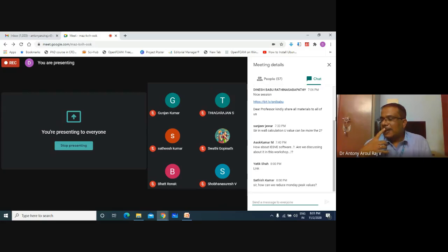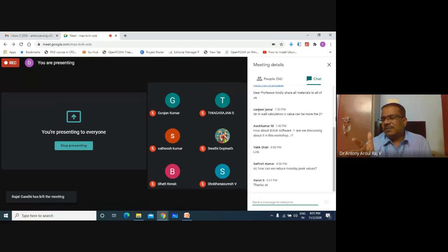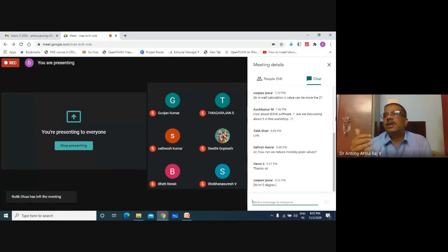And the thing is, your air conditioner will be working for a long time. That is why the energy consumption is more at that point of time. Your air conditioner will be working for a long time without cutting off. So that's why the energy consumption will be more. But if you go to day 2, all the residual heat has been removed. So continuously, it will maintain a low temperature. So that will be sensitive to external solar radiation only.